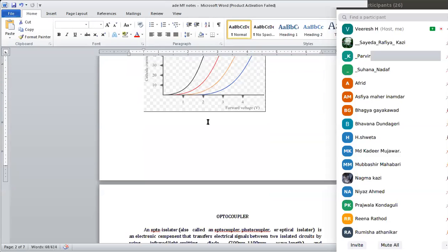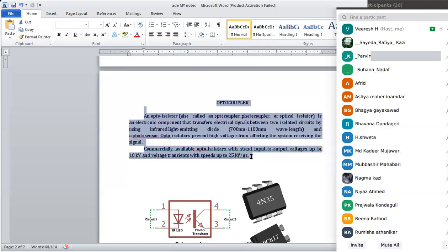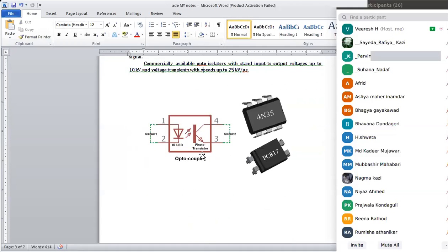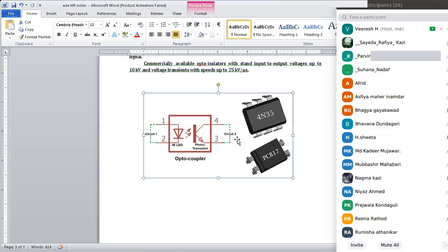Okay, this is about LED. And we have also discussed the optocoupler, right? It gives isolation between circuit 1 and circuit 2. This is an example, where one AC supply of 230 volts is connected to the Arduino controller, which is working on 5 volts on the other side. Do you remember that? Hopefully.